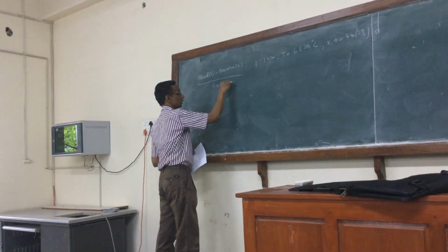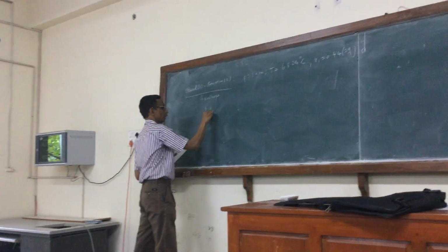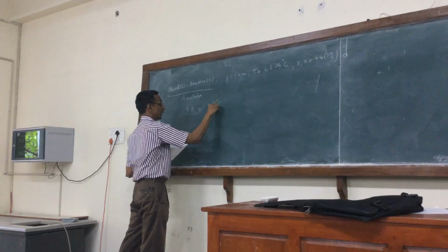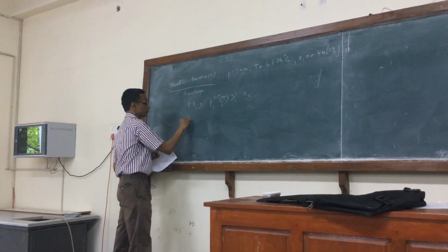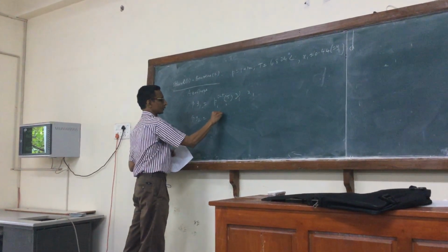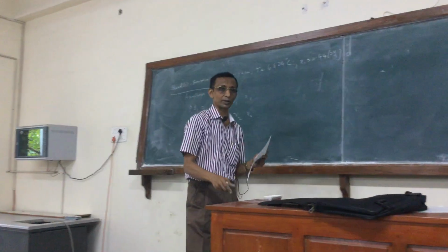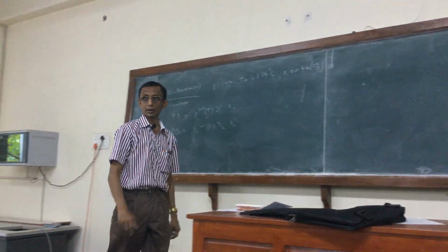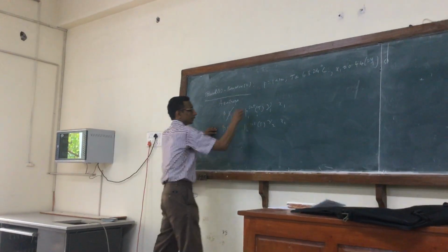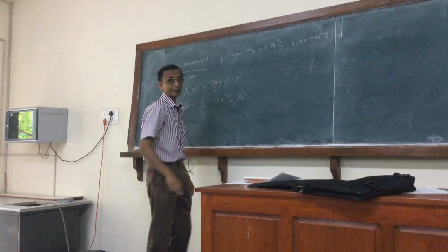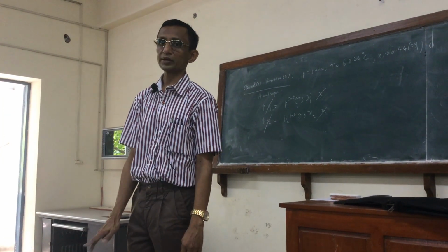And so, what we use is the modified Raoult's law. The modified Raoult's law says P y1 is, for a binary mixture, P1sat of T gamma 1 x1, and P y2 is P2sat of T gamma 2 x2. Now I'm going to apply these equations at the azeotrope. So y1 is equal to x1 and y2 is obviously equal to x2, y2 being just 1 minus y1. At the azeotrope, the mole fractions simply cancel out.